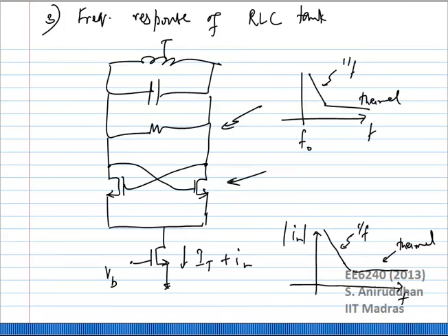And we said, okay, if it was just pure up conversion as in a mixer, it would look like, from the bias noise, you will have a 1 over F and then maybe thermal noise, right? As we are going to see in today's class, that is not exactly the way the oscillator noise looks like.